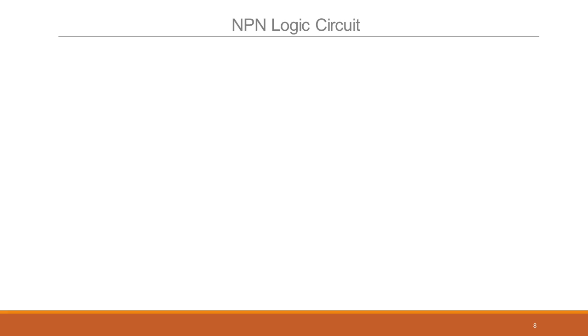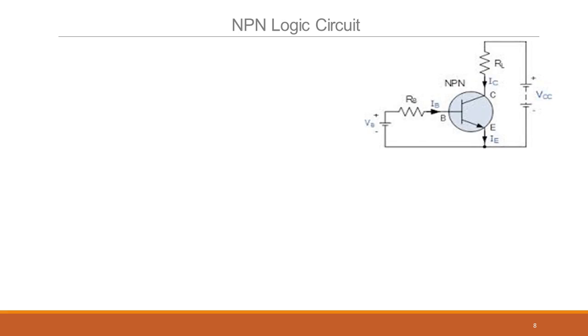We'll just take a look at NPN logic circuits. Let's just do two problems to quantify the learnings that we had so far. Let's say we have a bipolar transistor which has a base resistor and a collector resistor. The base is connected to a voltage source VB. The collector resistor is connected to a VC, right? So we have biased the base and are biasing the collector.